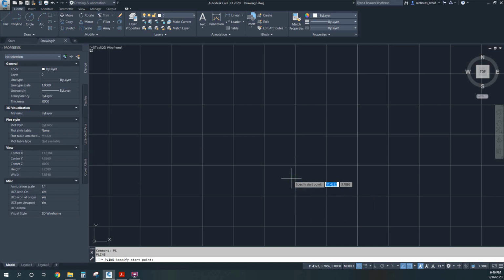I have never used half width, but I can see that in some scenarios it could be useful, and obviously people do use it, or AutoCAD would not have done that. And then the next one is length, where you specify the length of the line. You could click, drag it out and click wherever, or you could specify it, so if you want it to be 3, it'll specify the line length of 3. So that is the length portion of the POLYLINE.